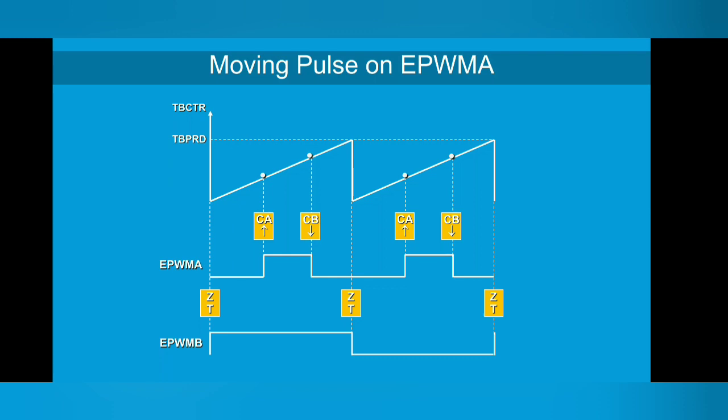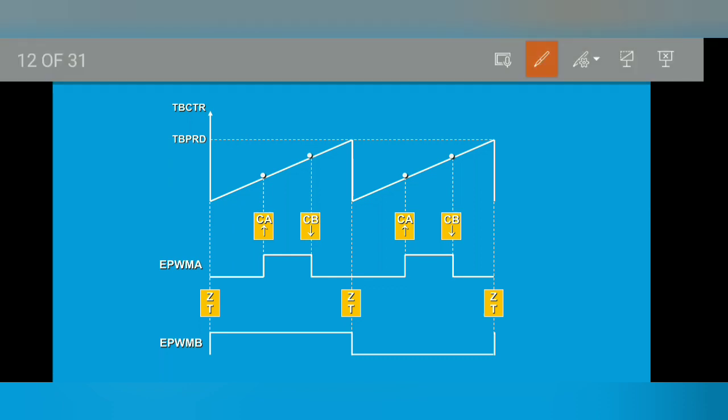So this is the same case but in a different way. For EPWM we are generating it when your TBPRD value is set in the time base control register, the compare A value will be equal to TBPRD. It will be making it high, and otherwise it will be making it low at this point.